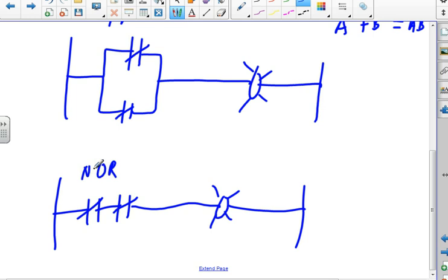All right, so I can look at this. Now, each of my runs of my ladder are numbered. So run 1, run 2, run 3, run 4, run 5. When I devise a numbering system for the wires in the circuit, those numbers will be based on what run I'm in.